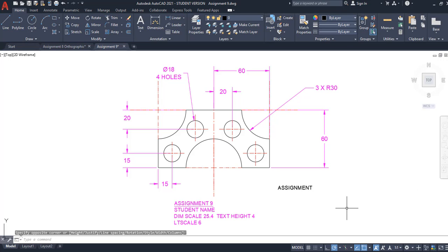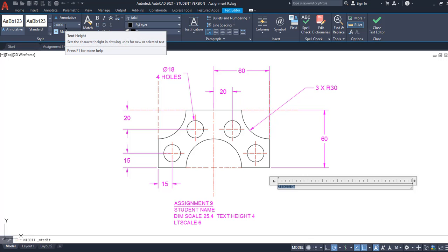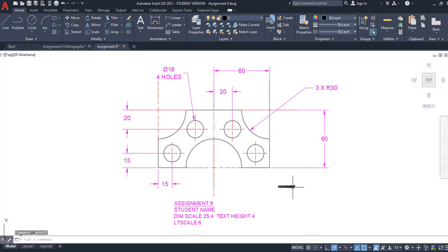Once you've placed it, if you want to change your text height, you double click on it, highlight the text, and then this is kind of sensitive a little. You have to click on the number at the top left corner and change the height, and then enter. So I changed it to be a little bit smaller. So just wanted to give you a couple of choices here.